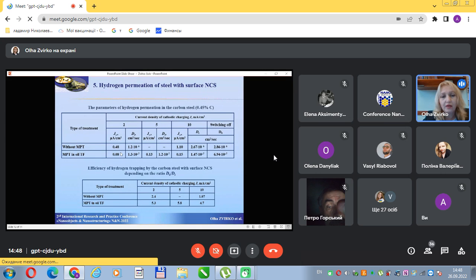And also, the effective diffusion coefficient is significantly lower than the largest one for the nanostructured material, which means more difficult conditions for hydrogen transport in the nanostructured material, which can be associated with high defectiveness of the nanostructured material. And what's more, this high defectiveness also resulted in a higher efficiency compared with as-received material.